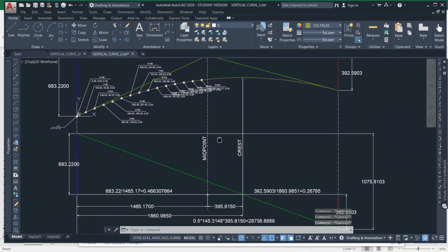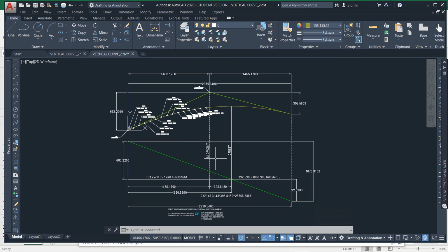And then the rest of it here is finding the point of vertical intersection. Sometimes you don't have a formula, you can't remember the formula. The rest of it is pretty much just a compound parabola. I don't know what you want to call it. It's a symmetrical parabola. It's not even a compound. Yeah, it is. So this is a single parabola up to here, and then this is another parabola up to there. If you know the parabola formula, you could find the high point and then just use the slope. You just use the parabola formula on either side. It'd be a different formula for either one. I'm not that keen on that.